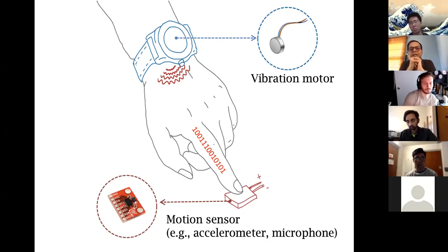Sure. There are definitely other sensors you can use, right? You can do NFC, near field communication, etc. But if you just keep it to vibrations, one of the ideas that came up in discussion with these companies was about the signal flowing through your bone. How do you model the received signal? The source signal convolved with a channel. Your bone is also a channel, right? So your received signal at the accelerometer, let's call it Y, is nothing but H convolved with X, where X is the source vibration signal and H is the bone channel.